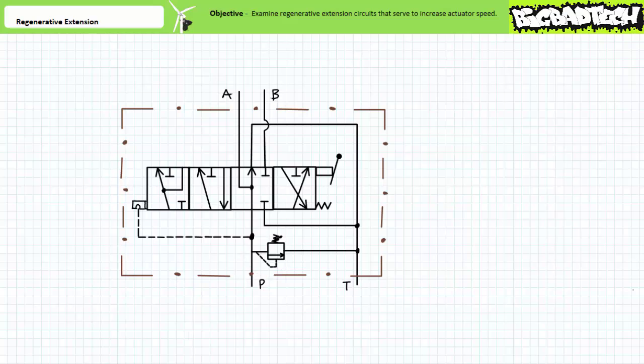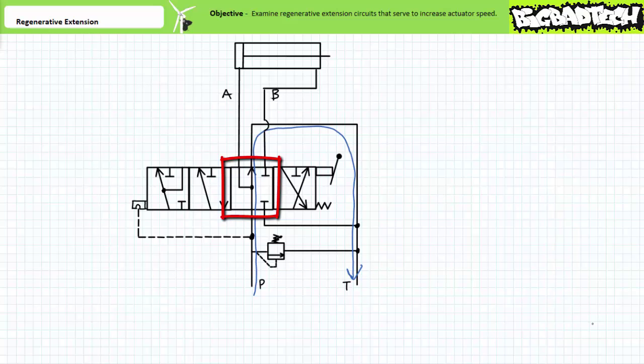Basically, all you need for this valve is a hydraulic power unit and a cylinder, and you've got yourself a complete system. If P and T are respectively connected to the pump and tank, and actuator ports A and B are respectively connected to the cap and rod end, see if you can determine how the various positions function. Note when the valve is spring offset into its deactivated position, pump outflow is routed to tank at low pressure, thereby keeping the main pressure relief valve closed. Additionally, note actuator port A is at low tank pressure, although actuator port B is blocked. This is quasi-equivalent to a tandem position.